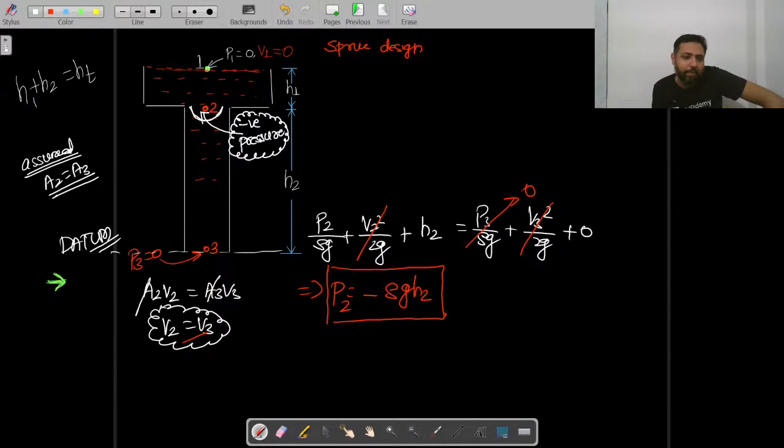So that is what is happening. This will appear like you are sucking out the metal. At point 2 molten metal was coming under gravity, but if you keep this cross sectional area constant, then it will start feeling like you are sucking the metal like this.